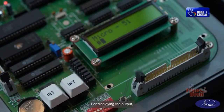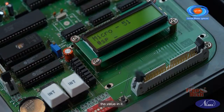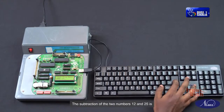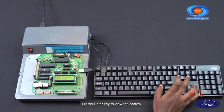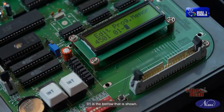For displaying the output, enter SP and the data pointer address where we stored the value. Here it is 4500, and click enter. The subtraction of the two numbers 12 and 25 is being displayed as 13. Hit the enter key to view the borrow. 01 is the borrow that is shown.